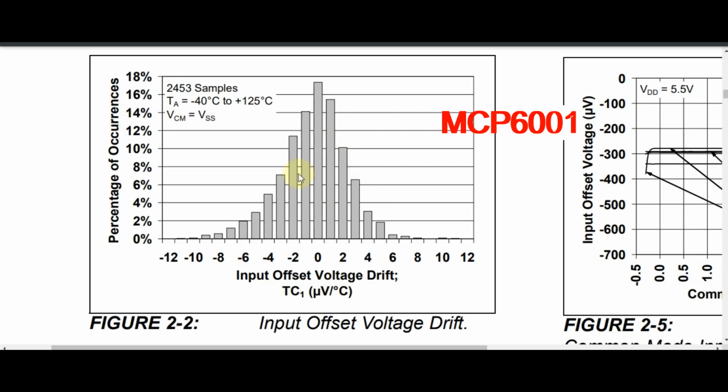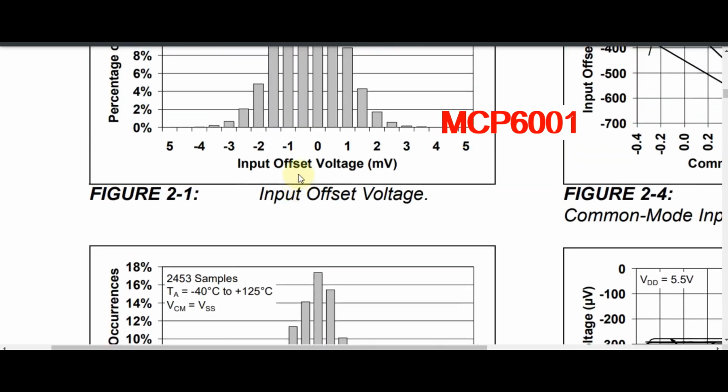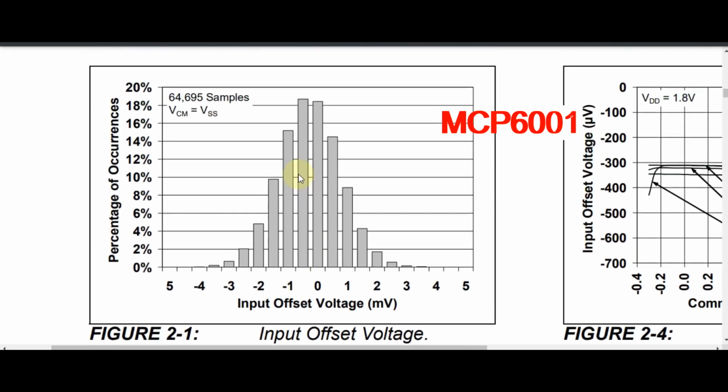I hope you have understood how to read the Opamp data sheet for input offset voltage, and how you predict what is going to happen in your production. What tolerance analysis you need to do, what variability you need to analyze for production, and what process capability you build up to accommodate this variability.